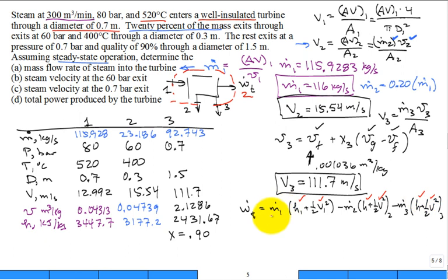And the mass flow rate in at 1, mass flow rate out at 2, the mass flow rate out at 3, those are all given. The only difficulty is what? Can you guess what the difficulty is? Where would a student make a mistake? Units, units, units, units, units. Because this term naturally is in kilojoules per kilogram. What's the speed in meters per second? You square it. How can those units be consistent if I'm going to add two terms and then multiply by the m dots?